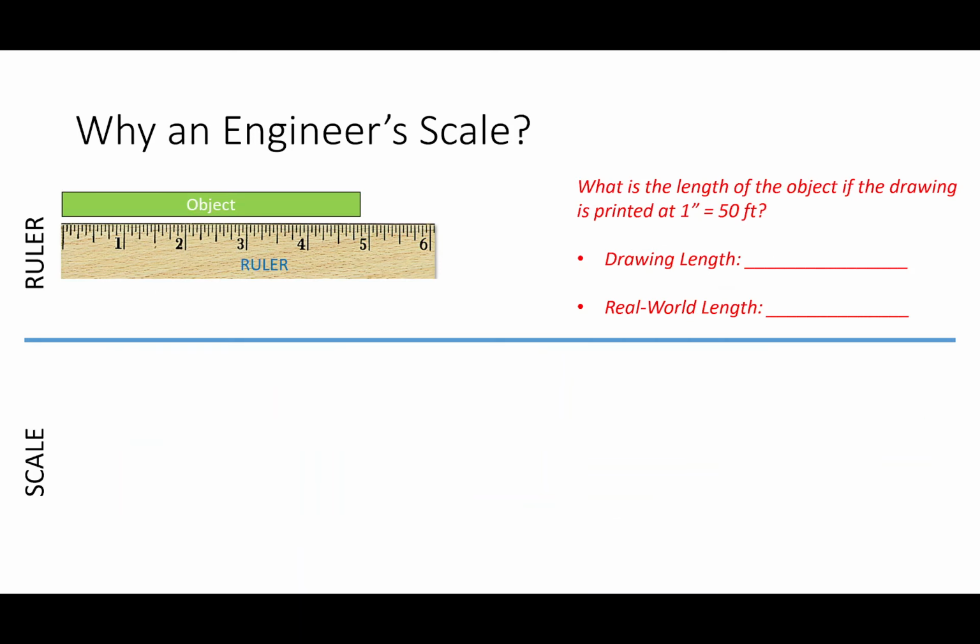Now, let me make the point as to how an engineer scale makes your life a lot easier, okay? I want everybody to look up here on the screen. I have here an object. This object is in green, and I want to know the length of this object in the real world, okay? Let's say that this object is printed on a drawing such that 1 inch equals 50 feet. So what do I do with a ruler? I go to a ruler and I measure the length. Looking at this screen, I think that length is about 4 7/8 inches. Does everybody kind of agree with me on that?